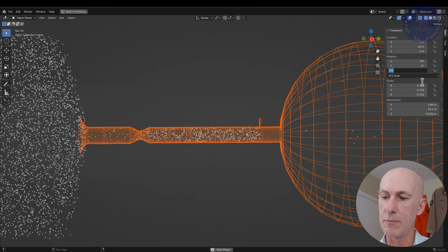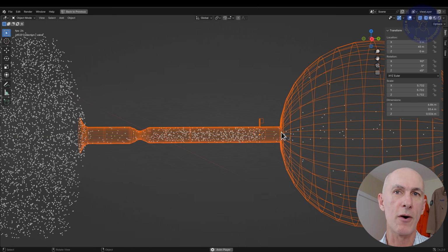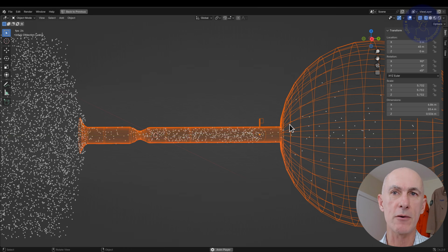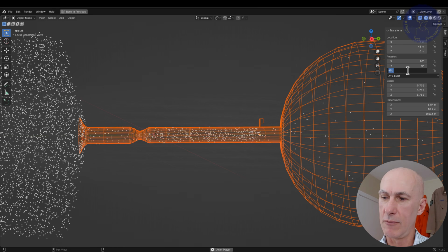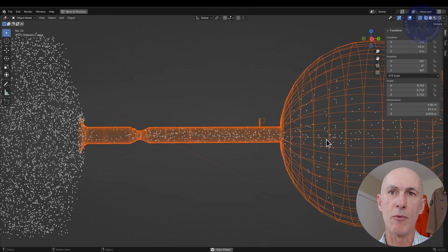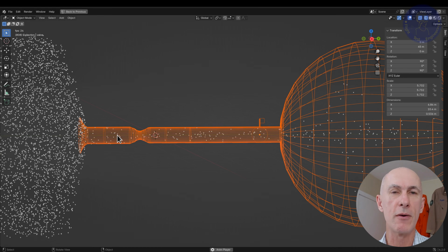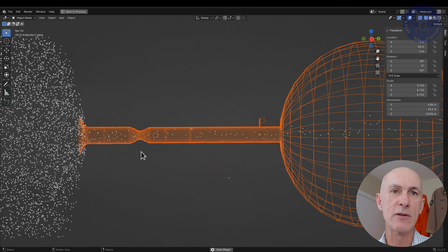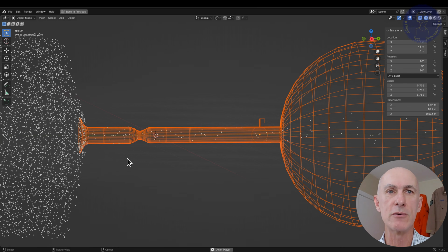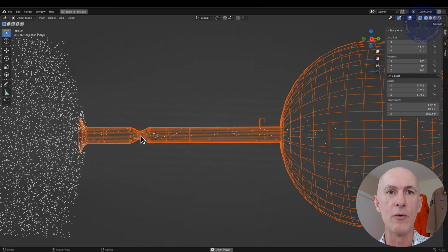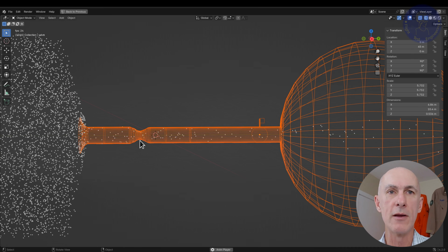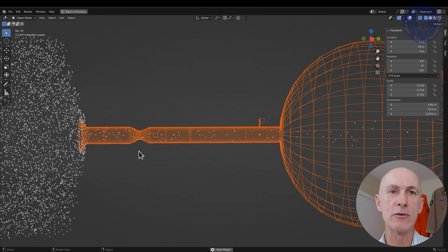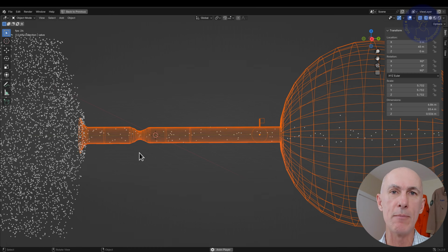And as we open it more and more, 45, of course, we would expect more and more particles to flow into the sphere. And if we fully open, yes, more and more particles are going to flow, accelerating the flow on the throat here. But as we said, this is going to have a limit. This is going to have the limit when the flow reaches Mach 1 here, right at the throat. That's going to be when the flow is going to be said to be blocked.